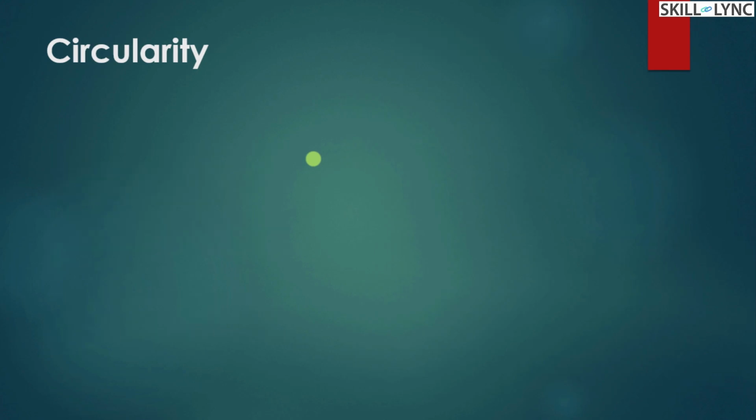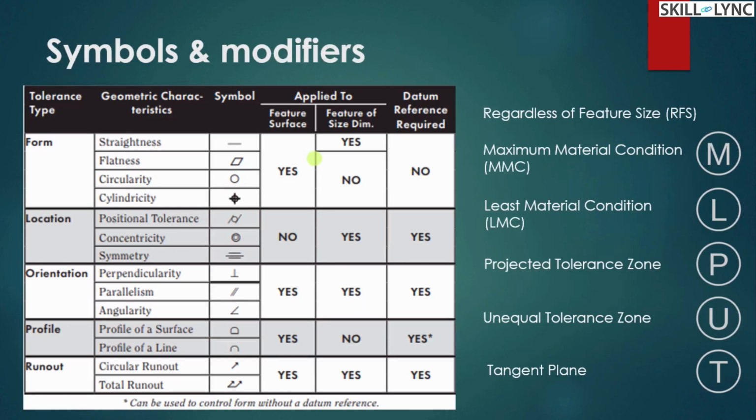So let us go back to this definition once more. So you can see now we have seen straightness, flatness, circularity and cylindricity. Now these all apply to this thing. So there is just a difference between here. These two are wrongly represented. Cylindricity is represented by this and position tolerance by the other symbol. But these four are going to be your form tolerances.